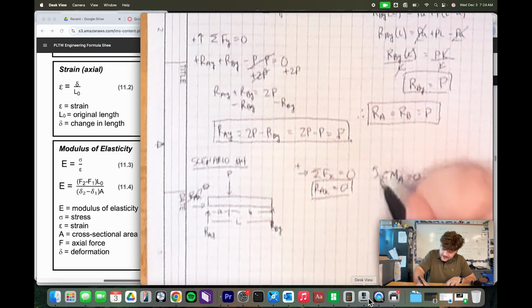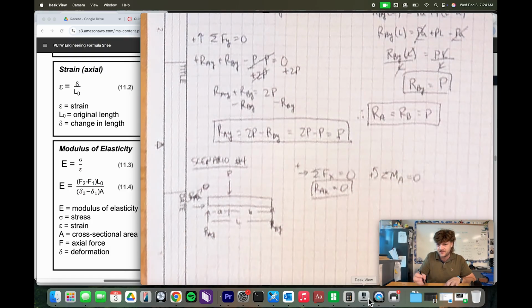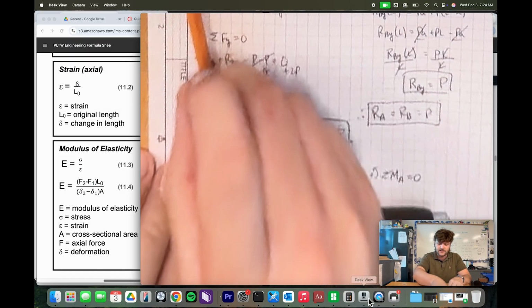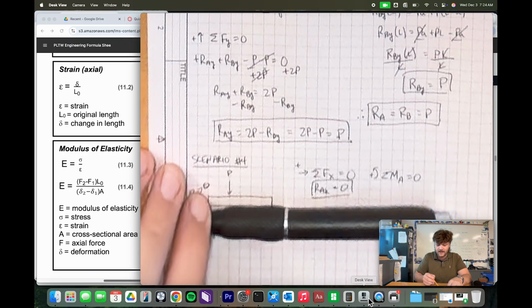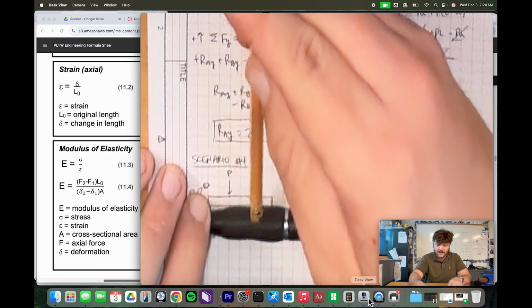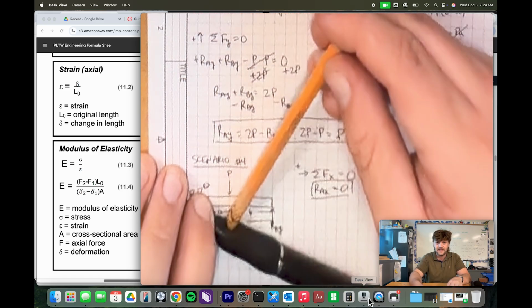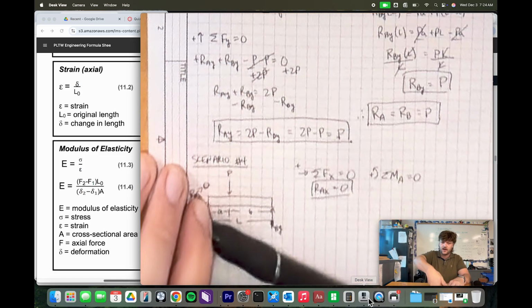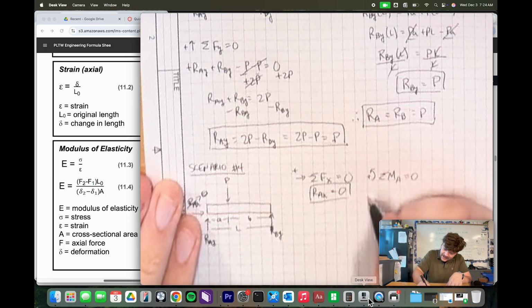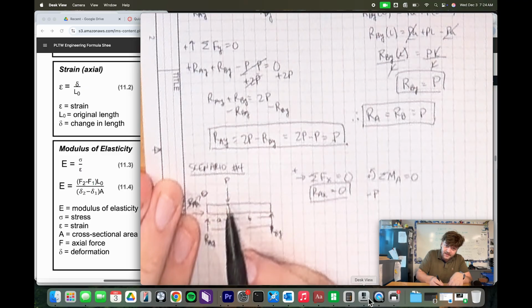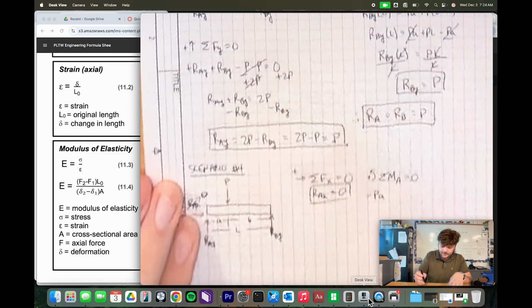Remember, we want to specify that counterclockwise rotation is going to be positive. And so now we can calculate the moment about point A. What I'm going to do first is simulate the beam. It is hinged at point A, right? Which is the point we're calculating the moment about. I'm going to go ahead and push on our beam at point P with a concentrated force. And as you can see, that is starting to cause our beam to rotate clockwise, which is going to be negative. So we're going to take the force, which is P there, multiplied by that distance A.